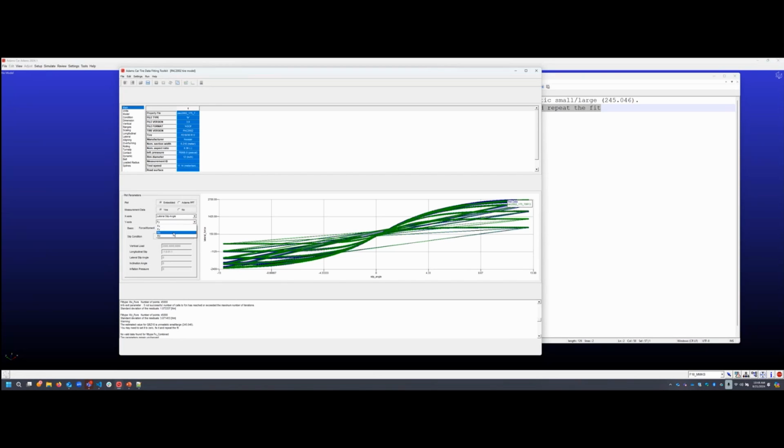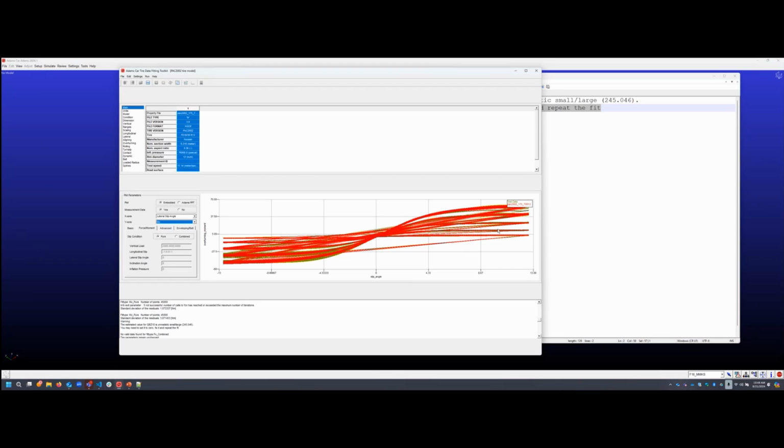We'll check all the other stuff also. We'll check the overturning moment. This also seems to have a decent overlap. Of course, it's not going to be perfect. It's trying to fit multiple different curves and adjust the coefficients within the tire. It's not going to be a perfect fit, but it'll be as close as you can get it. And this is pretty decent in general.